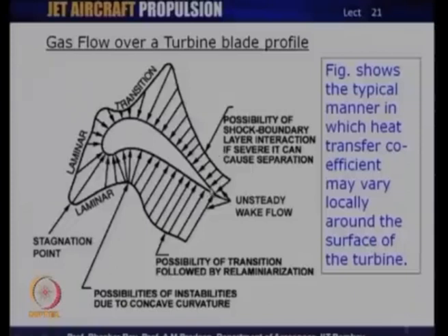We also know that somewhere near the trailing edge, there could be another local stagnation point, which would become another hot spot, because the local temperature there would be equivalent to the stagnation temperature. There are many such areas over the gas turbine where the blade is extremely sensitive. The suction surface of the blade, which participates more in the working of the gas turbine, needs to be protected, and as a result, you need to provide differential cooling over these gas turbine surfaces.